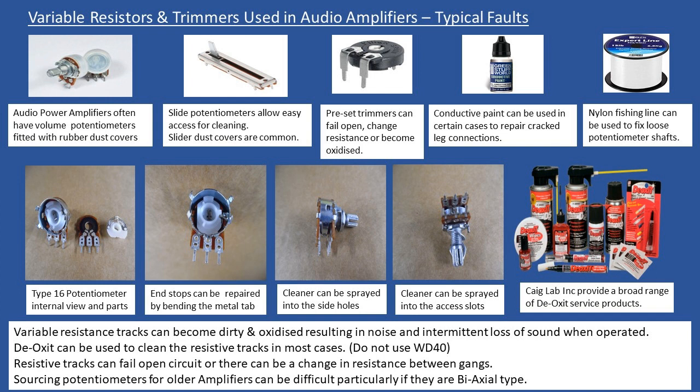So what I do here is you can use nylon fishing line, and what you can do is literally pull the motor shaft forward around from the collar, and then just tie some fishing line and rotate or wrap it around just a couple of times and then tie it off. And what that does is it fills the gap between the collar and the potentiometer shaft. Okay, and then it's just a simple case of putting some lubricating grease around there, and it's like fitting a nylon slip washer.